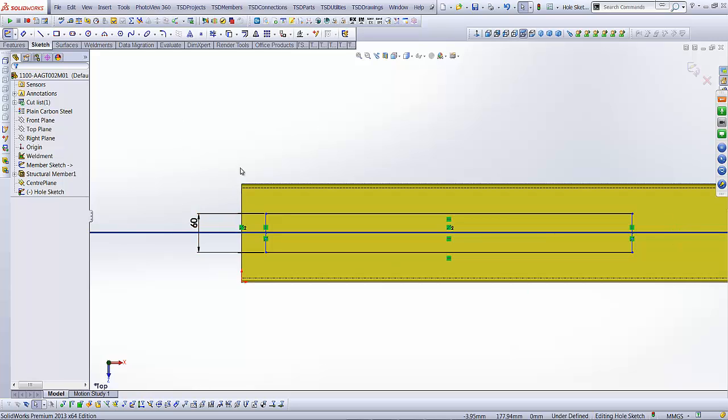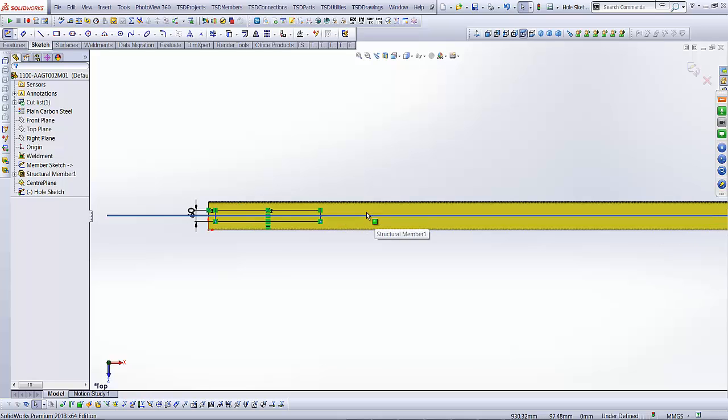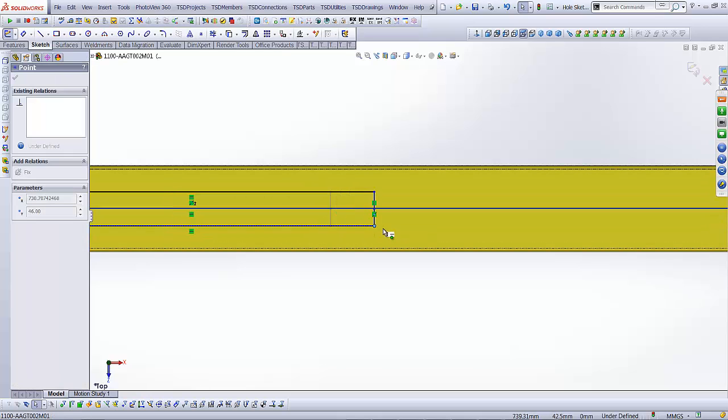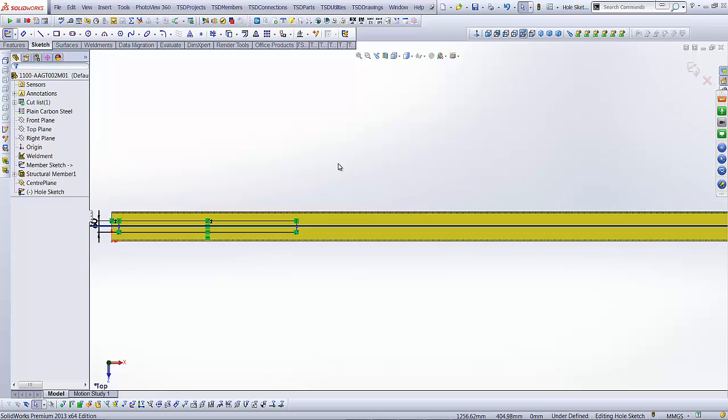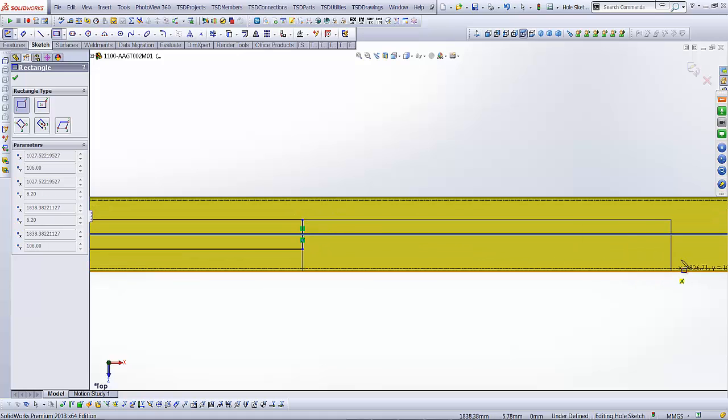Also, you'll notice that I haven't fixed this to the end because we've got to do a trim of 5mm as well. So I'm going to put that trim plane in as well, and I'm going to shift it up the tree in front. But what I want to do is just get the holes started, okay? And we can come back and lock this sketch down. So there is going to be a centerline of bridging, so I'm just moving that rectangle out there, and I'm just going to snap the next rectangle in.